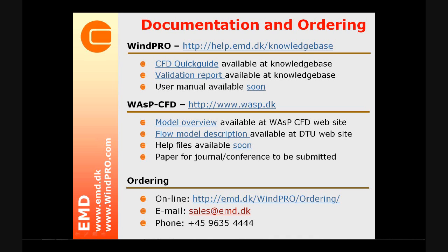Yeah, well, I have several questions with this, with the wind speed, and again, for instance, what wind speeds are we simulating, are we using when we do the CFD simulations? And the simulations are actually done with a logarithmic profile that has 10 meters per second at 10 meters height. But the CFD speed-up factors that we are calculating would be exactly the same if I did it with 1 meter per second or 20 meters per second. Because we have removed these effects, they are completely independent of what wind speed I'm simulating.